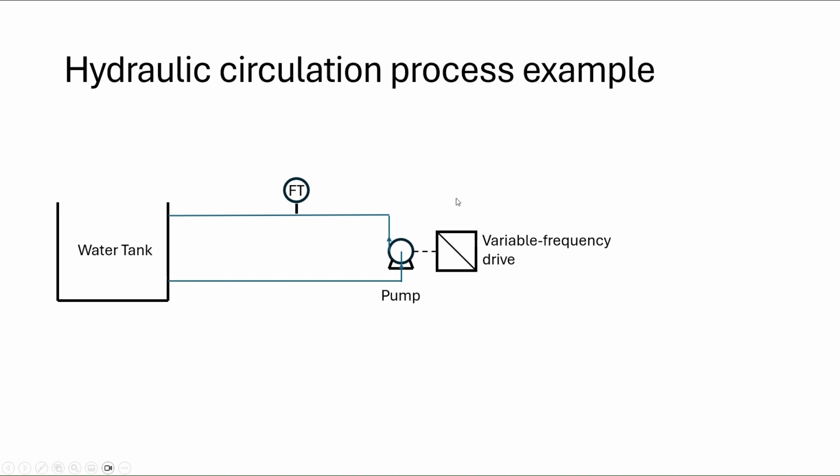Let's just make that proportional, and that's actually the signal that the digital twin will generate, and the digital twin will give that to the PLC. So the digital twin in this case is just one basic formula. The model consists of that formula, and that is connected then back to the PLC with this flow transmitter signal.